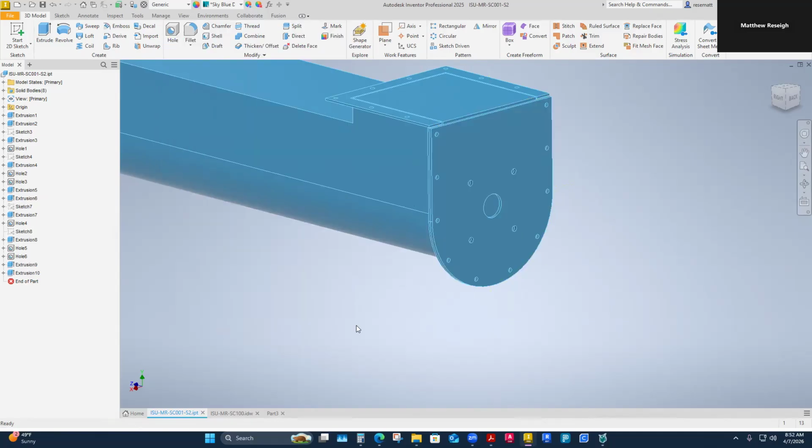This kind of stuff happens when you put a new day and a new set of eyes on it. My go-to gut would be that I wish my bearings had the same studs in the ends to support both bearings with the same fastener. Unfortunately, just by the nature of the bearings I'm purchasing, I can't get away with that. I don't want one to be a really sloppy fit, and the other has to be a 7/16 because I can't use a 1/2 inch bolt over there. I'd have a size on size issue, and it'd be hard to slip over the bearing onto the studs. You'll see what I mean when we make the studs.